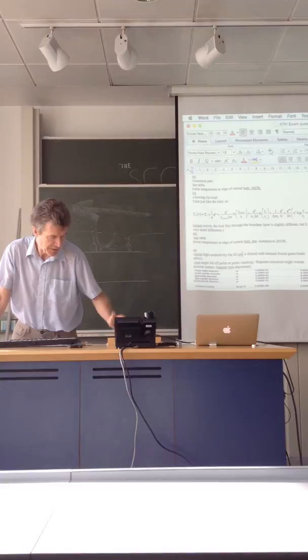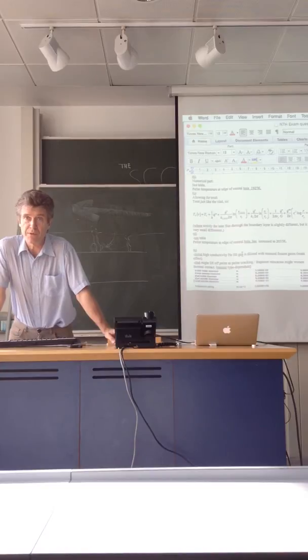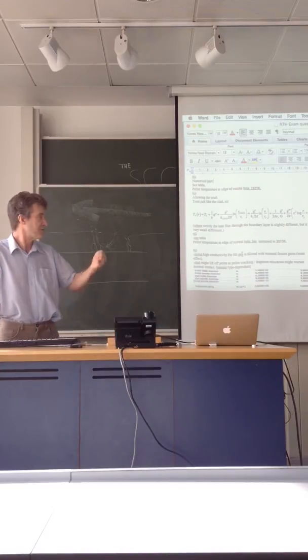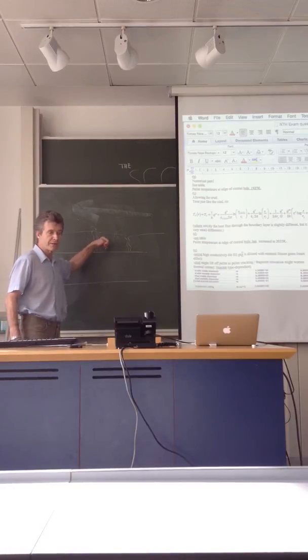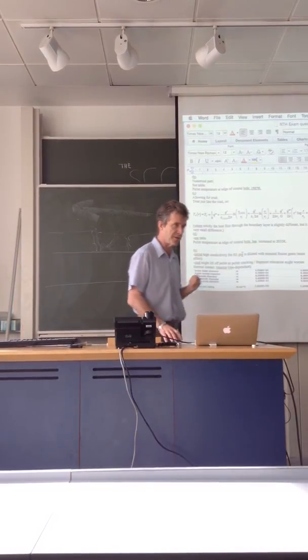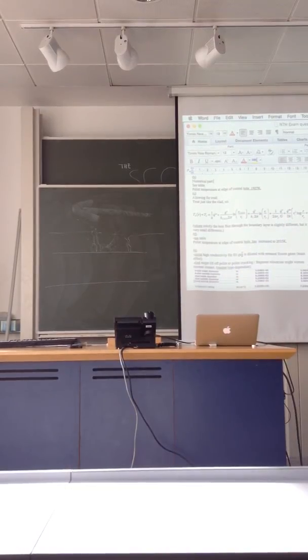And of course, any chemical engineers will know, if you have highly concentrated solutions of stuff, you're going to change the boiling point quite significantly. So you get a positive feedback that you get a lot hotter temperatures here than you might have thought, because the concentration of all these dissolved solids is so high. But that in turn affects the temperature distribution through the crud, it affects how the heat is getting conducted.